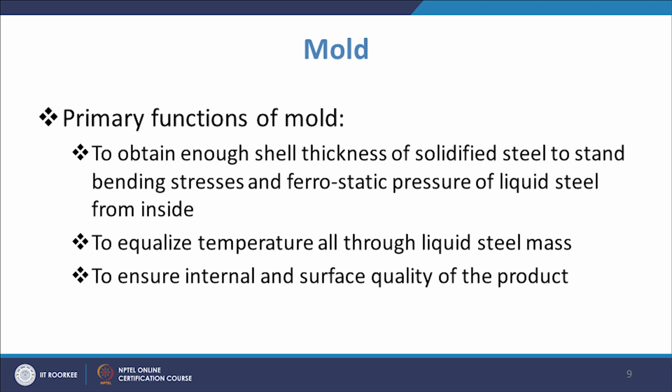Its job is also to equalize the temperature all through the liquid steel mass. It must ensure proper temperature, otherwise there may be different structures on different sides, and that also ensures the internal surface quality of the product, because cracks or other kinds of defects are likely to be generated by improper cooling conditions in the mold. So there also it is ensured.